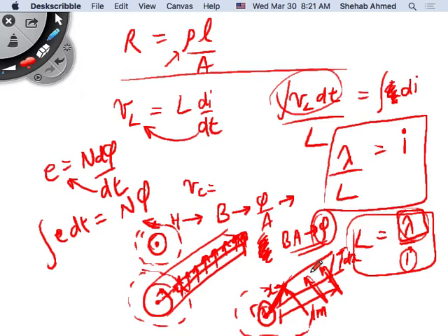Outside the conductor, these flux lines are encircling the conductor, the full conductor. Inside the conductor, it's linking one turn, right? So outside the conductor, this flux that we've calculated is linking the one conductor that I have. So if I go to Faraday's law, what is n? What is the number of turns that I'm linking with this flux? 1 if I'm outside the conductor.